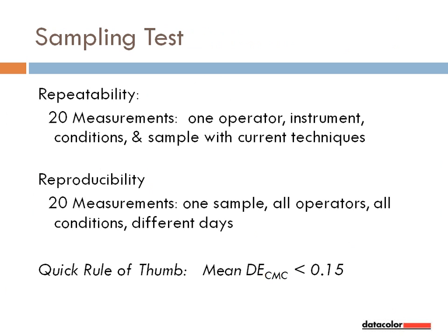Presuming one uses stable sample material, a recommended rule of thumb or goal is to maintain process uncertainty, an average color difference among attempts, at or below the factory-specified inter-instrument agreement of the spectrophotometer models in question.